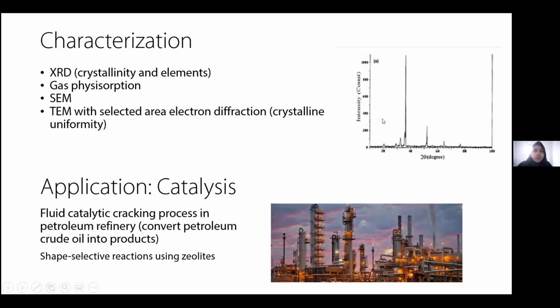And the application of nanoporous materials is very wide, but the one that is focused in this lecture is catalysis. Nanoporous materials are used in fluid catalytic cracking process in petroleum refinery. It converts petroleum crude oil into products using shape selective reactions of zeolites.